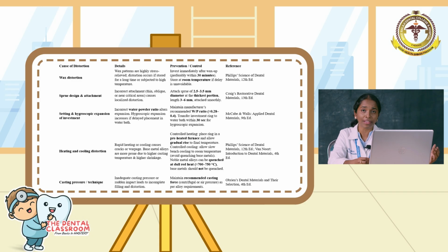Next, setting and hygroscopic expansion of the investment. Incorrect water powder ratio can also contribute to distortion. So always follow the manufacturer's instructions for the water powder ratio and transfer the investment ring to the water bath within 30 seconds of the hygroscopic expansion.